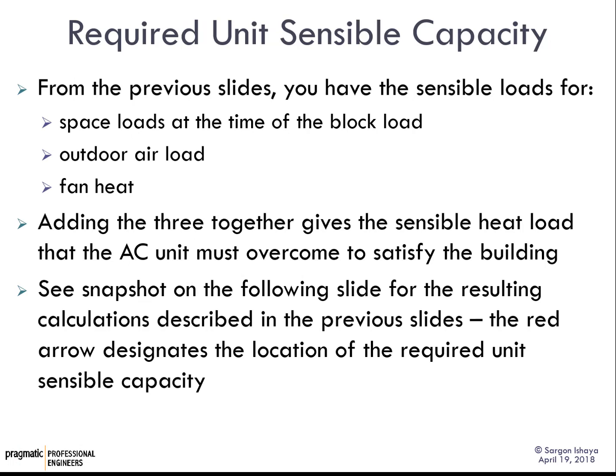Now, we're still moving on here, selecting this package unit, which is laborious, but after you do this a few times, it'll go very quick. So, from the previous slides, we have the space loads at the time of the block load. That's from the system checksums report. We have the outdoor air load, and we have the fan heat.